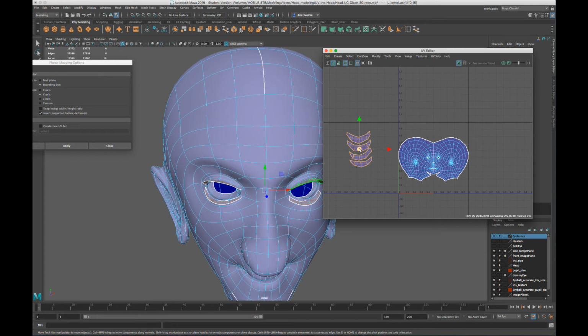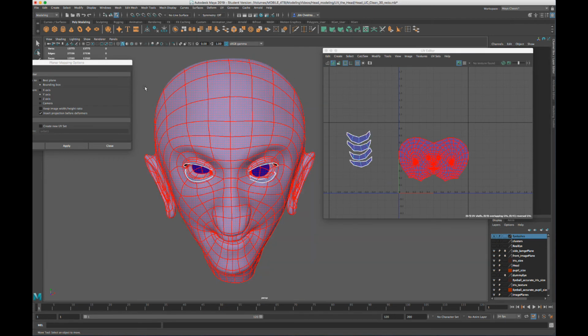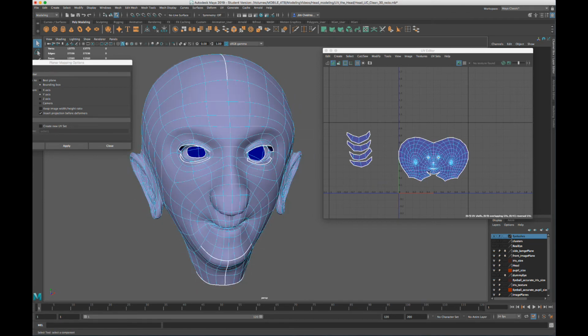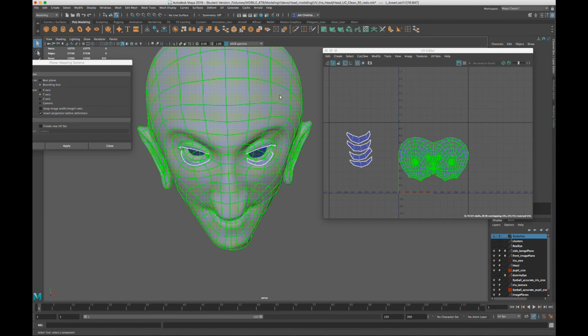Now, if that was not too understandable what to do, it depends on what you're making this for and how fast you want it to run. If you want everything to run in real time, the best idea might be to find a solution to have just a small transparency card only for these, in the same way we did the feathers for the body. It just might not make much of a performance difference, but what I'm going to do for this particular model, I'm going to have a separate small map just for the transparency of the eyelashes. Not combine these at the moment.